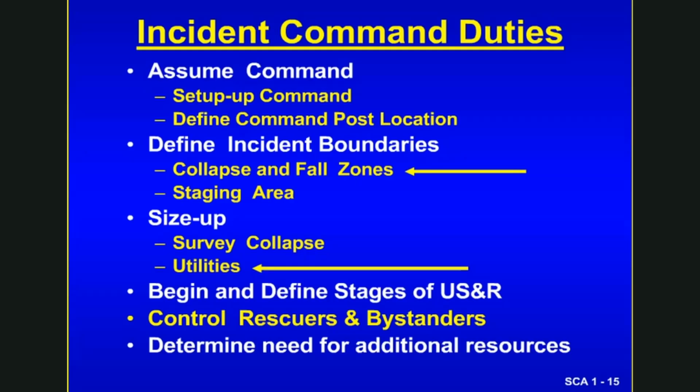He'll do a size up, which we've already talked about, survey the collapse, and make sure the utilities are taken care of, shut off, tagged out, and begin and define the stages of urban search and rescue. And then he'll control the rescuers and bystanders and determine the need for additional resources. This is, of course, somewhat of a repetition of what we've already talked about.